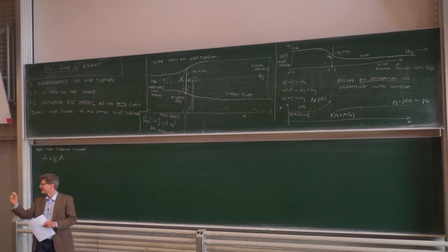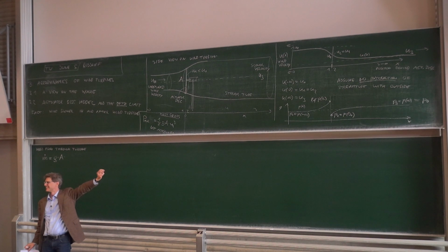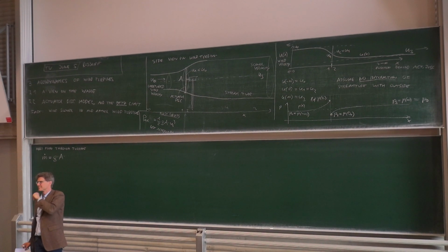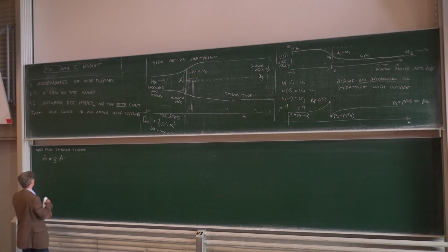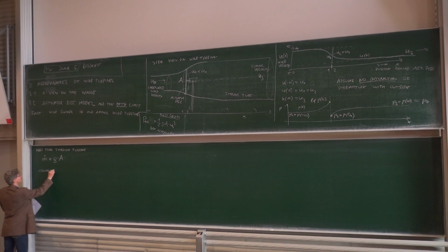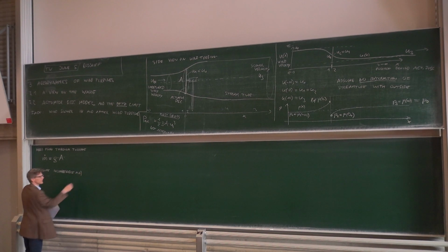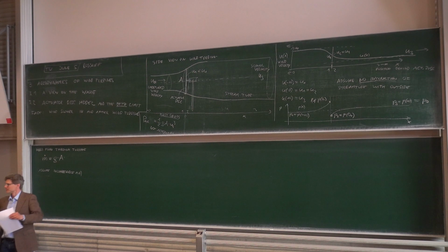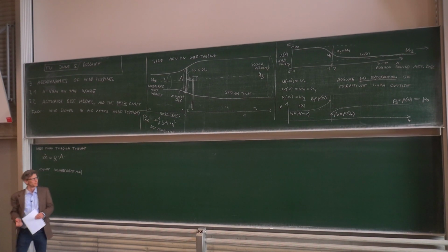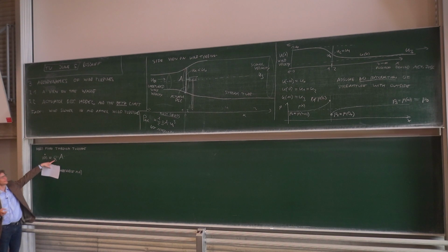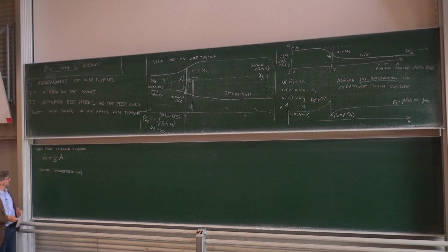Because the air is flowing through the disk with a different speed than we thought before. Yes, to be very exact, density would vary a bit with pressure. The variations are so small here that we still regard it as incompressible. For a very refined analysis, this would also be necessary to include. So assume incompressible air. It's a good question, actually. Air is obviously not incompressible, like liquids nearly are. You could compress it yourself when you pump up your bike. But if you pumped up your bike with water, you could get a very high pressure without any compression. For wind turbines, the effect is not as strong as in the pump; the pressure differences are little. So we can safely assume one value for rho, like the one we had before. But it's a very good point. Thank you for the question.